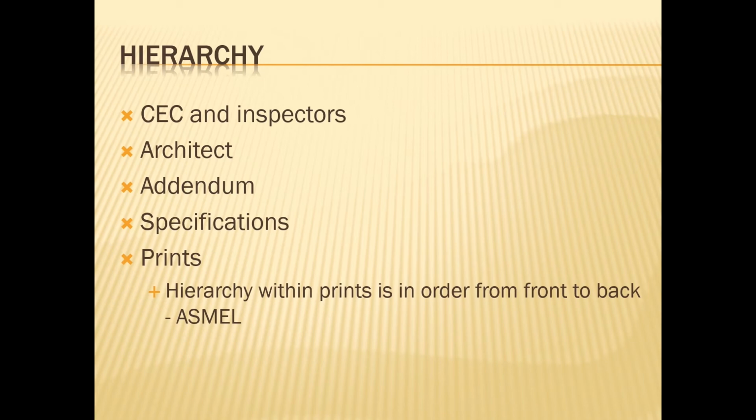As we go through the drawings from architectural to structural to mechanical and then to electrical and then to the landscaping, the hierarchy follows the same pattern. So whatever is mentioned on the architectural drawing will take precedence over whatever is mentioned on the rest of our drawings. So it's important for us to be able to cross-reference other drawings to make sure we have the right information.